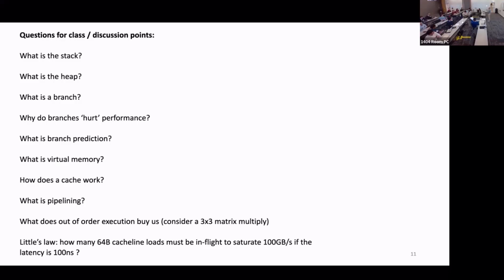Yeah, that's the vague. Okay, so when you have a pipelined chip, it's very often advancing and fetching the next instruction, decoding it, assuming consecutive execution of instructions. And when it deviates from that, it's done a bunch of work that it has to throw in the bin and cancel, right? And that's called a misprediction, for example, right?